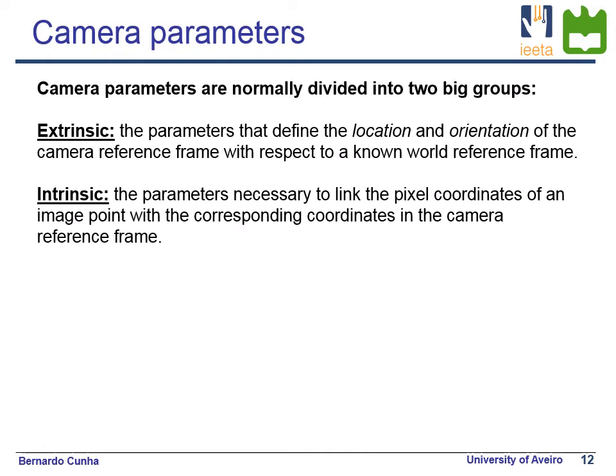From the original discussion, what should start to be apparent is that in order to obtain real-world information based on a 2D image on a camera, you have to perform a set of geometrical transformations, because the camera will be located in relation to the world coordinate system at a certain angle, in a certain plane.